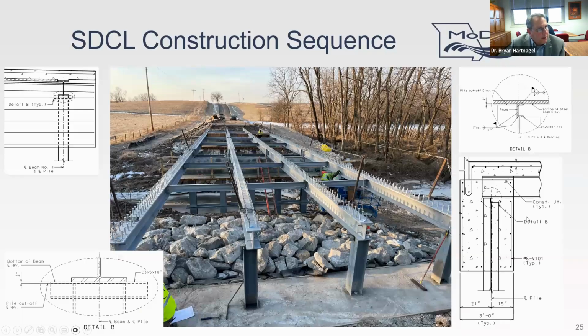Here you can see one that's basically got all 3 spans set up there, and you go, well, wow, look at this. They just set the beams right on the piles. This was another in the design build. We allow approved alternate standards. So if some other states do this type of thing, the design build contractor can propose that, and we'll look at it. And initially we thought, well, no, but then we set big plate girders on girder chairs as well. So this is kind of similar to that.